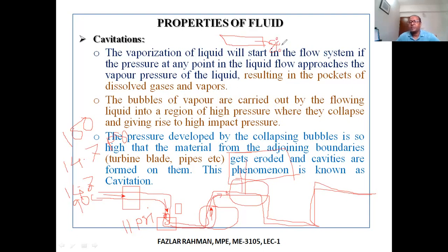It is happening with cavitation because due to the rotation, you learn the Bernoulli's equation. We'll teach you later on. Right over here, velocity of the fluid is increased, kinetic energy increases, so pressure decreases. Due to pressure decrease, it gets some bubbles. And this bubble suddenly sometimes collapses and hits your propeller blade.